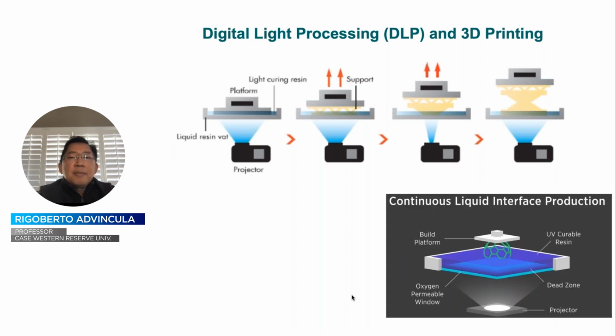Now, talking about different types of innovation, so almost 5 or even almost 10 years ago, people have looked at photochemistry and controlling the amount of radicals present or oxygen that quenches these radicals during the photopolymerization itself. So several patents were filed, which eventually led to the CLIP process. They have shown that it is possible to control the speed of photopolymerization by the presence of an oxygen permeable window that enables the initiation to take place, or initiation and propagation, or any control of the radical species present, to limit the polymerization directly at the surface.